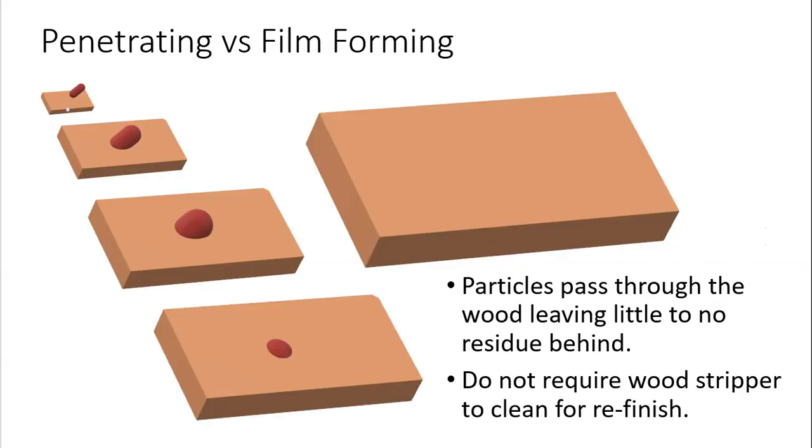Another benefit, as a penetrating particle passes through the board, it leaves very little to no residual finish once it passes through. And the most important point to understand about this is that because it penetrates so well, it does not require a wood stripper to refinish. And the importance of that will become very clear later on in the webinar.